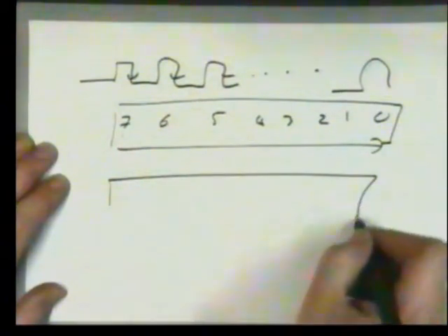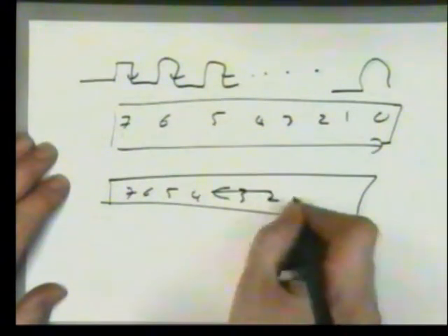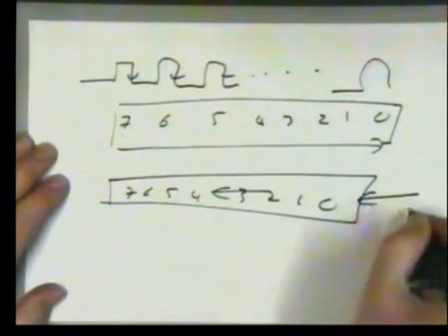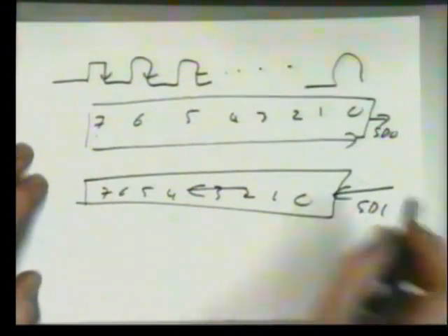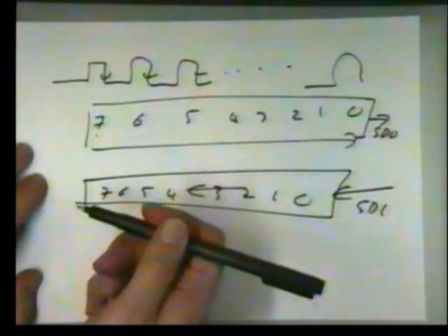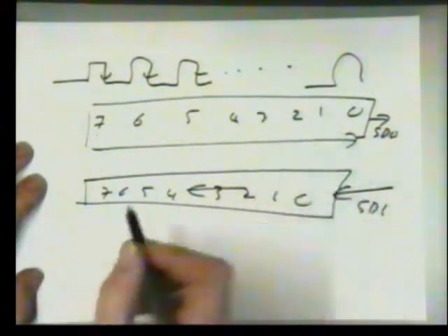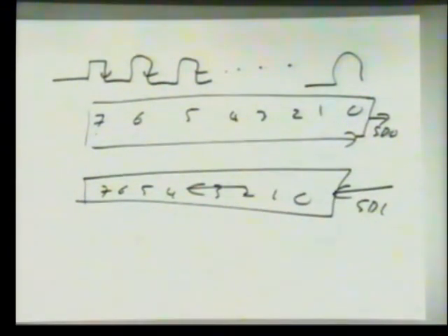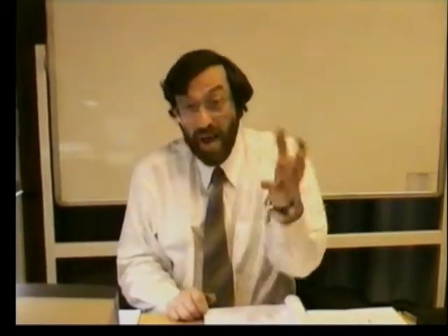Now at the same time we will be receiving back 7, 6, 5, 4, 3, 2, 1, 0, a byte from the slave device on the serial data in line. So we've got data going out and data coming in simultaneously. It's always transferred as 8 bits in a byte, and it's always most significant bit first. So it's a very simple structure. A clock, data out, you clock a byte at a time, and data in, you receive a byte at a time. Full duplex. Think of the software implications of this.